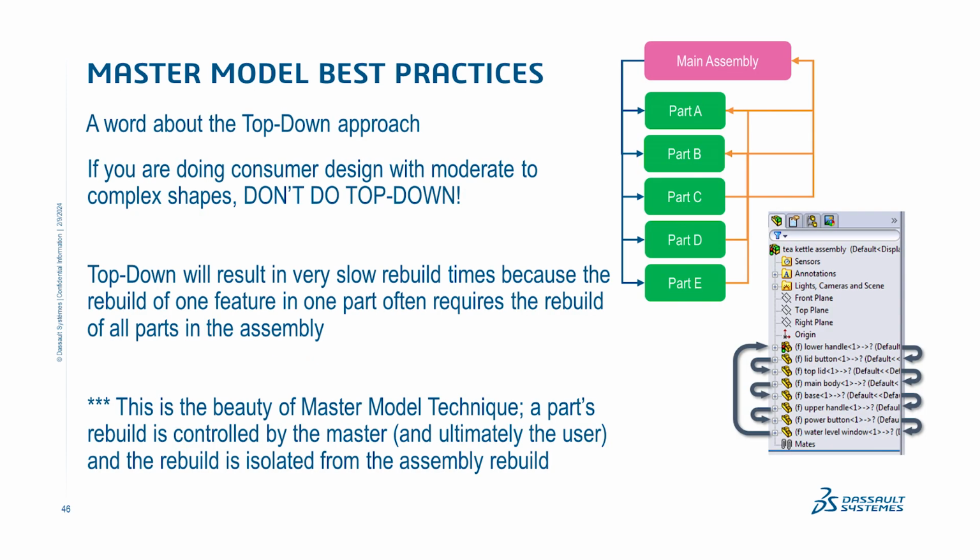Now you might want to be asking, Mark, why don't I just do in-context assembly modeling like SolidWorks has advertised, where you have an assembly and you have parts in your assembly, but those parts are making reference to other parts in the assembly. This is a valid technique, but what I found over the 20 plus years of using SolidWorks is that it's not very scalable. And it's actually not scalable at all if you're talking about surface modeling.